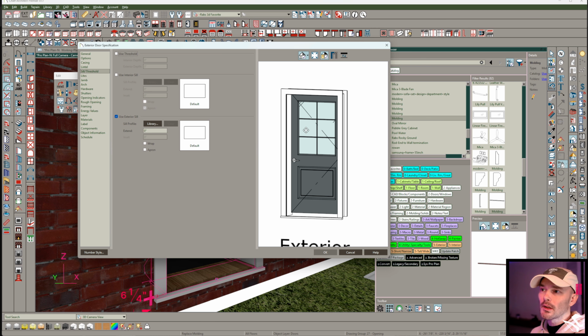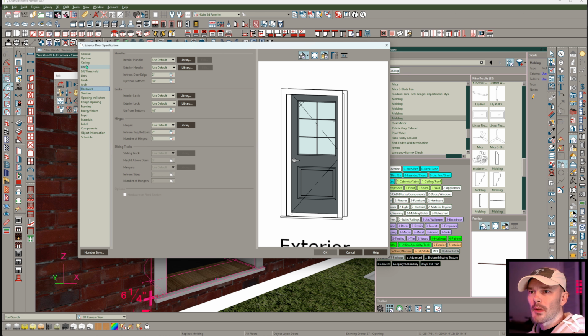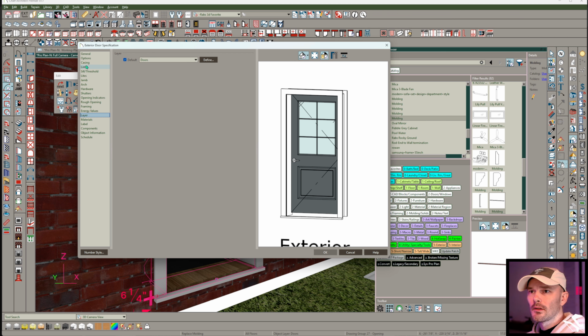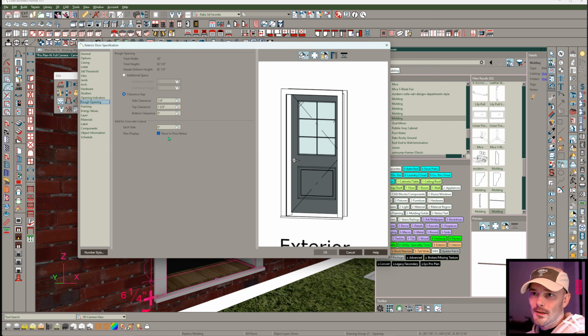We'd have to go dig through all the menus to see what that is, but it clearly did not replace that exterior sill. If we go look through all the menus, maybe it replaced something else. Who knows? You can maybe track it down from the materials here and see if anything's called brick. It's not. So toggle replacement mode for millwork is not working here.